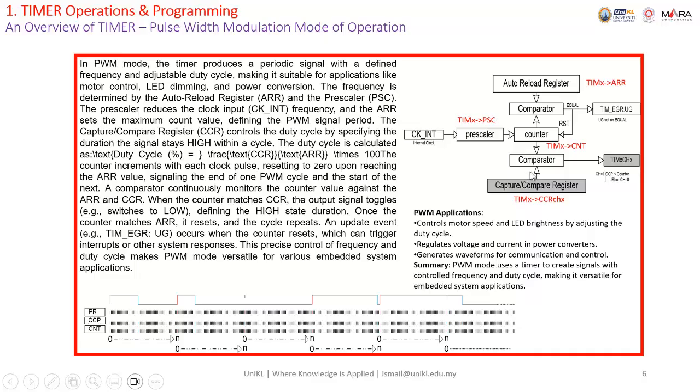That means from 100 to 1000, the output is 0. So 100 clocks are 1 and 900 clocks are 0. You can see that the duty cycle is 10%, 100 over 1000.